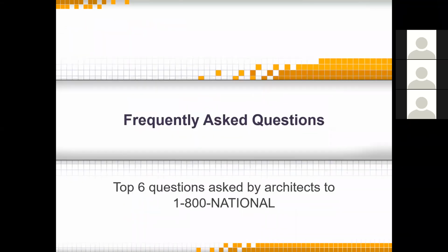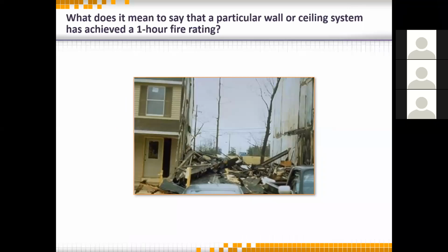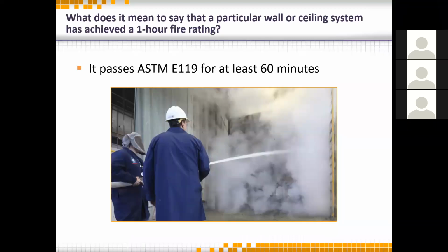So let's start to close out things with the most often questions we get in our technical department that relate to fire. The first question is, what does it mean that I've achieved a 1 hour fire rating? Well, what it means is that we've passed the ASTM E119 test for at least 60 minutes, and we passed the hose stream test, right?